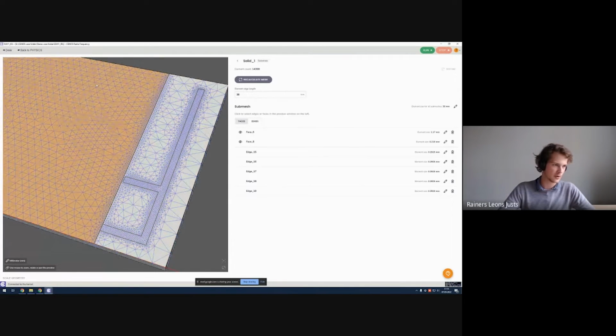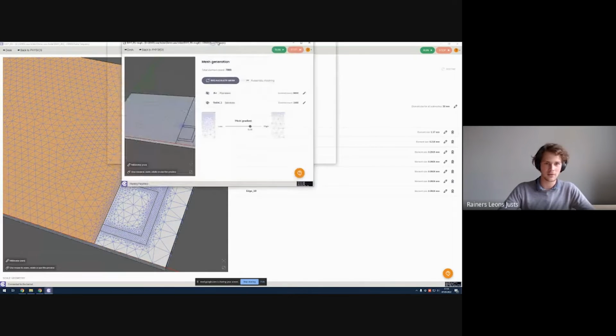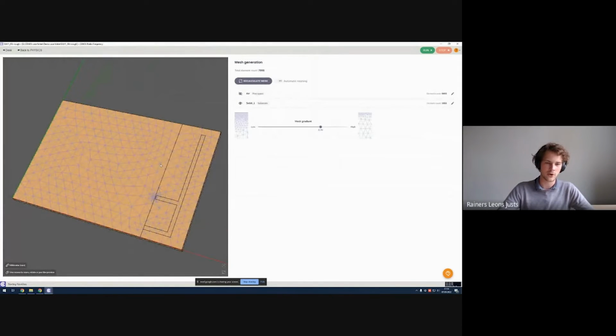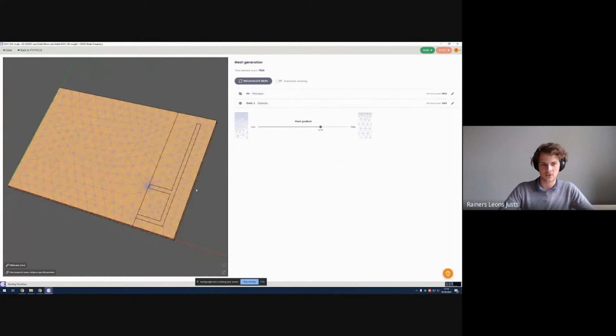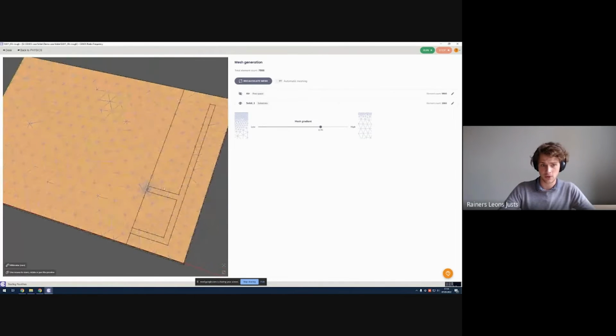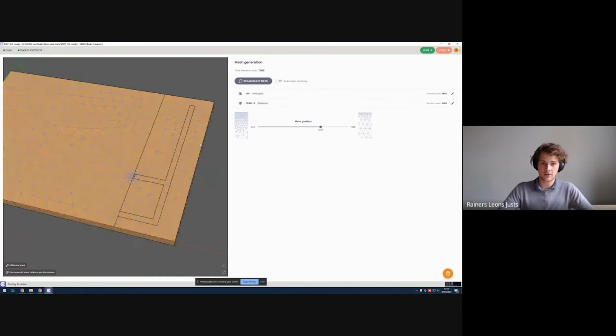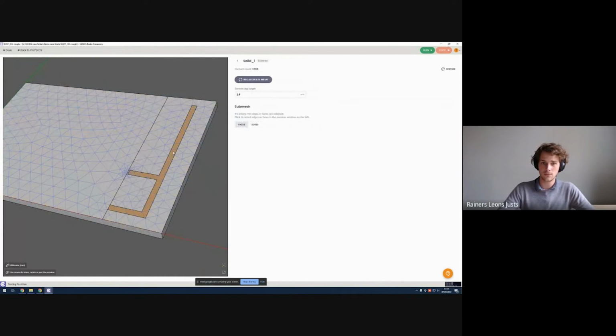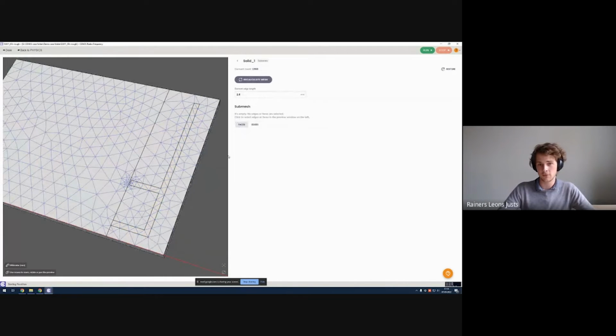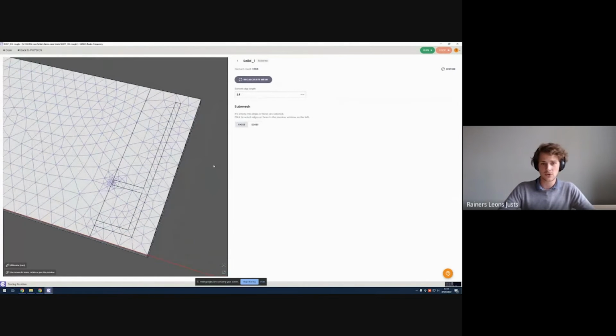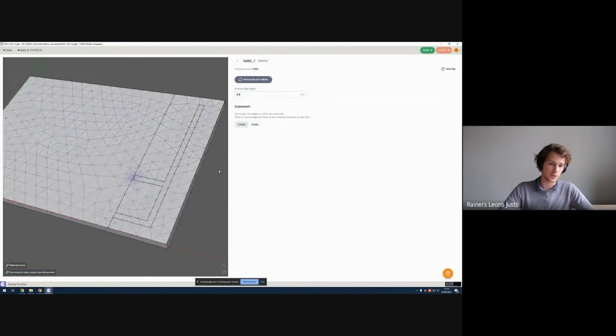instead I will be showing you how to adjust the mesh with an extreme example. I have already removed all the manual parameters, automatic meshing parameters as well. So as you can see, this is the model that we saw before in the presentation, where the model is extremely roughly meshed. And let's mesh this to be actually a lot better. So let's start off by going into the substrate role. And let's start off with some face refinements. In order to do some face refinements in our model, we just have to select the face that we want to mesh more finely.